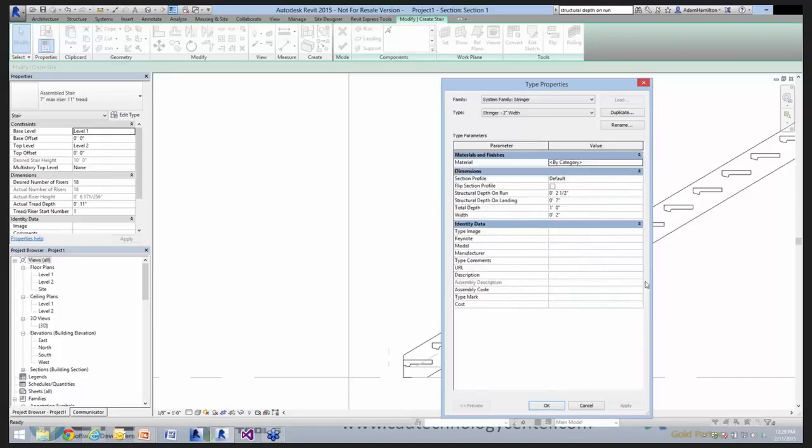Okay. But what we have inside the stair type for supports, whether you're tucking them around, is that they do have types. I'm going to go in there because, again, we have materials. Those materials, especially if it's painted, you might need to duplicate and call something like steel painted, a color, or polished. But the profile we use, the section profile, by default we've always been using this 2-inch wide by 1-foot depth profile, and it's amazing how many buildings I've looked at and opened up, and that's what I see, and I'm just kind of like, I know that's not how they're building it.